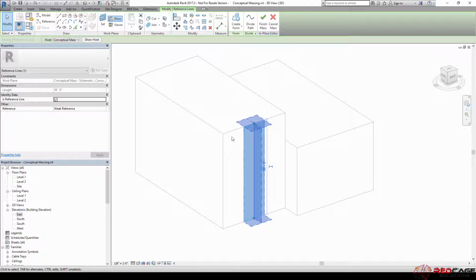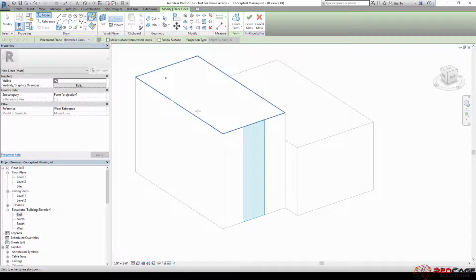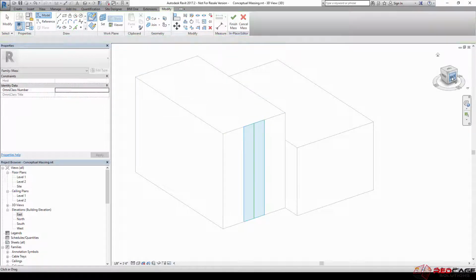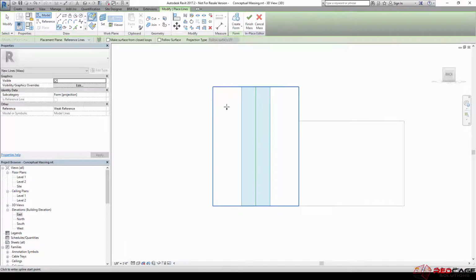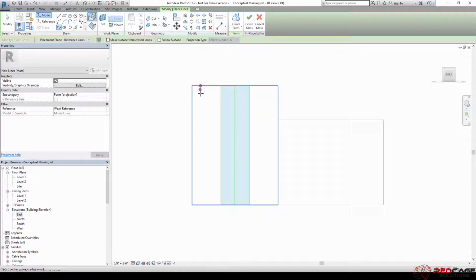So now what I want to do is draw another closed profile in here that I can revolve around this axis. I'm going to switch over here to my spline by points tool, and actually let's just look at this orthographically first. And there we go. Now I'm going to draw again on this face, and let's just draw something, a little hourglass shape in there.